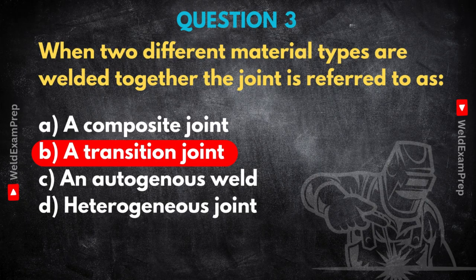Transition joint, okay. Yeah, it specifically means joining dissimilar metals. And it flags up that there are often special challenges involved. Like what kind of challenges? Well, different metals expand and contract at different rates when heated and cooled, right? So you can get high stresses building up, leading to cracks, potentially. Potentially, yes. And also, metallurgically, the metals might not mix well. You could form brittle phases like intermetallic compounds right at the interface where they join. That weakens the whole thing. So you need special procedures, maybe special filler metals? Often, yes. You need a filler that can bridge the gap, metallurgically speaking.